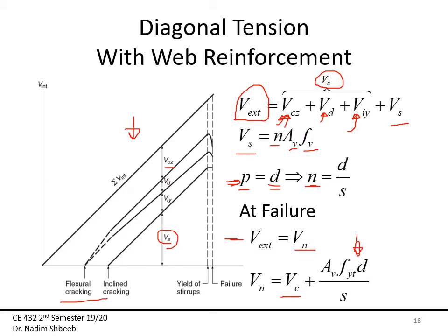You will notice that these three parameters are actually very hard to determine exactly, but again, from numerous experiments, we will always be able to find what I call an empirical formula to determine the strength that is due to concrete. As for the strength coming from steel, this is simply the area of the reinforcement times usually the yield stress of the reinforcement.